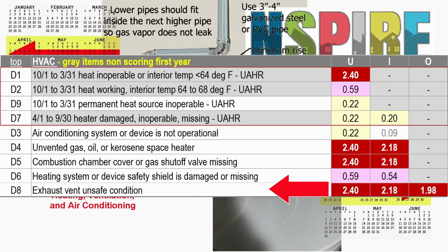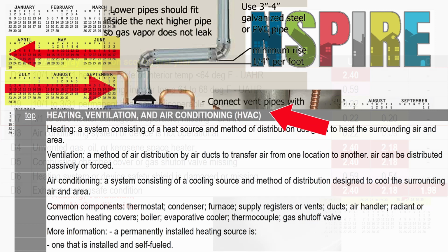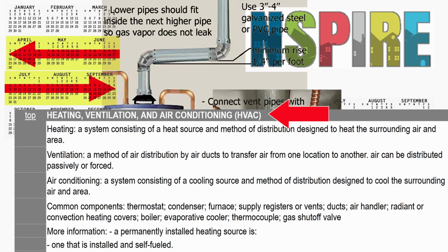Deficiency 8, you've got an unsafe flue or chimney. There is a carbon monoxide hazard due to potential unsafe venting of carbon monoxide gases due to the unsafe chimney or flue. Let's look at the longer definitions for more details.